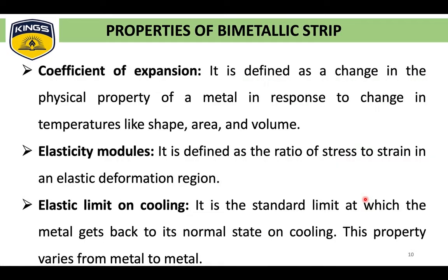Properties: coefficient of thermal expansion, which is defined as the change in physical property of the metal, like shape, area and volume, in response to change in temperature. Next, elasticity modulus, which is the ratio of stress to strain in the elastic deformation region. Elastic limit on cooling is the limit at which the metal gets back to its normal state on cooling.